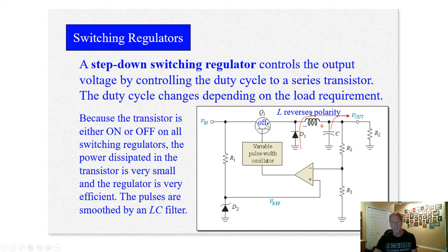This is shown as a BJT. It's normally a FET. Now, we have this inductor and catch diode and capacitor, this LC filter basically here, which filters out the switching waveform from coming through the transistor. So it just takes a taste of Vin and dumps it into this capacitor, which causes a step down function of the switching regulator.